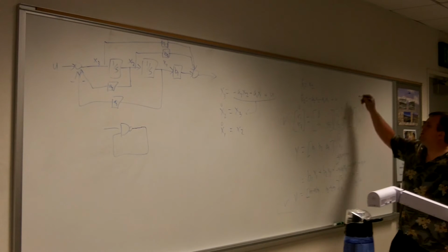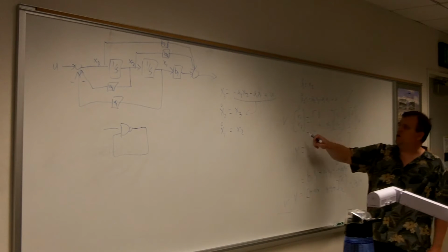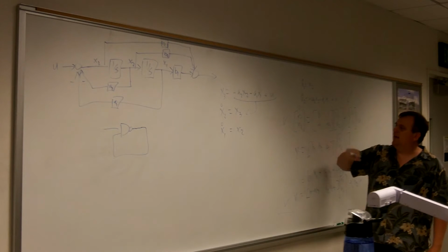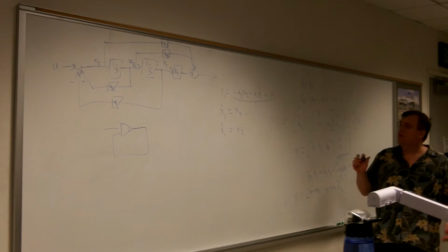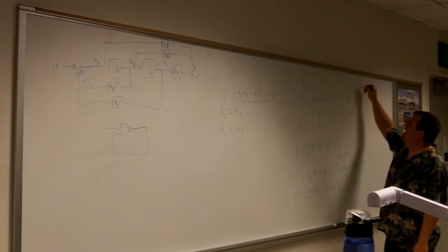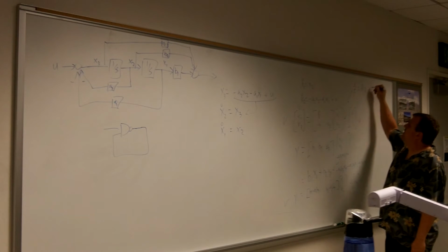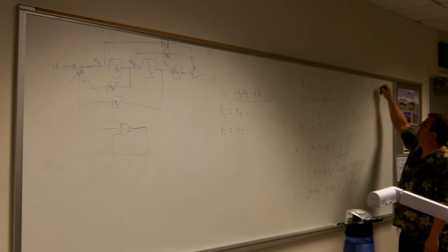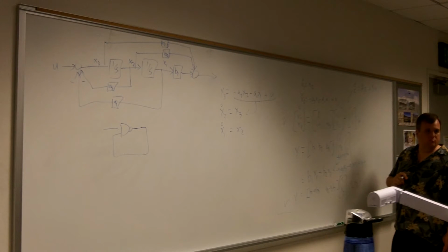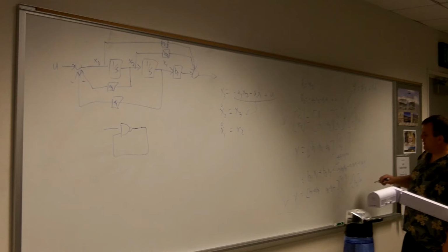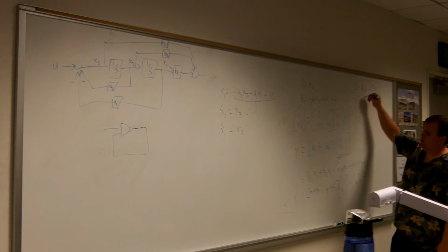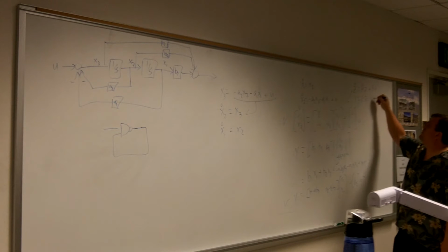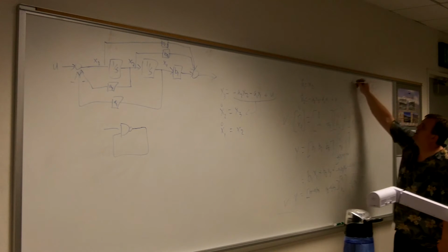Yeah. Now notice, this is of the form, let me just call x1, x2 that z. Fair enough? Just pick a new variable name. So that means this looks like z dot is equal to az plus, we'll call this b times u. Well, using that same naming convention, this last one down here looks like y is equal to some other, I've used ab, we now call it c times z again, plus next letter is d times u.